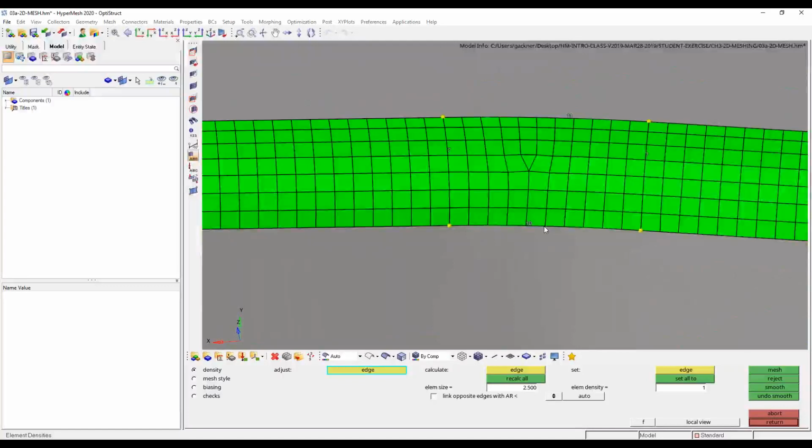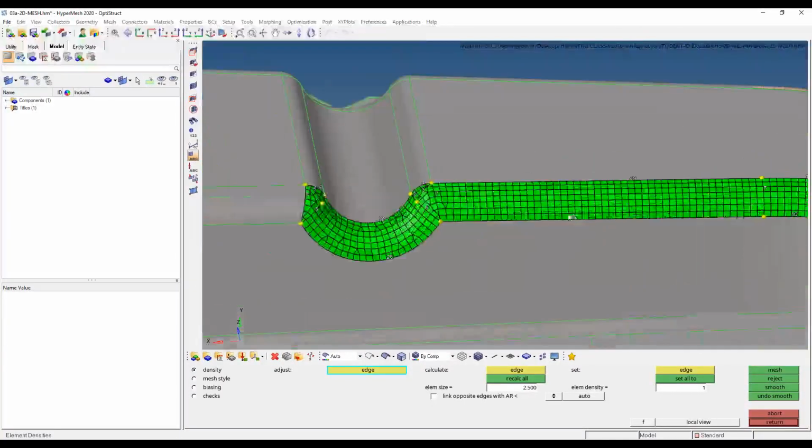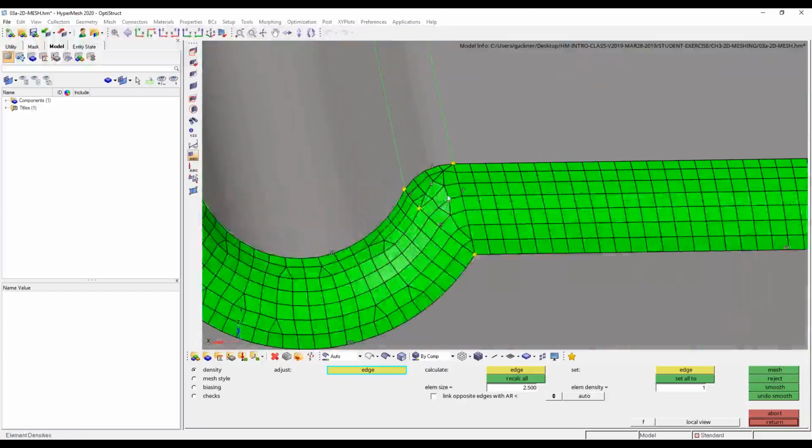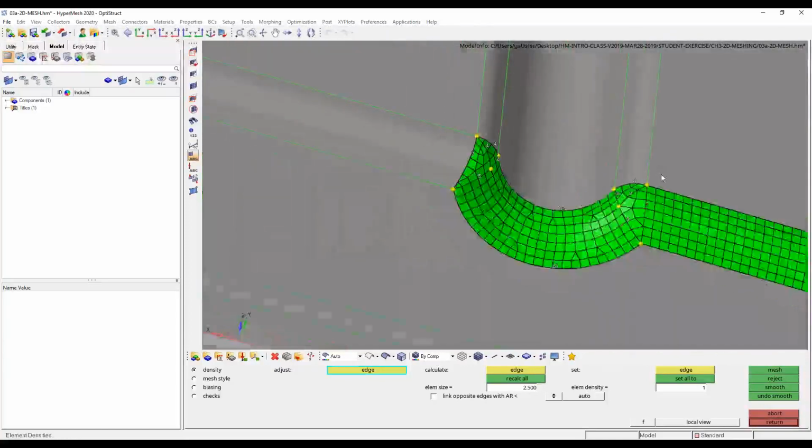Same thing over here. We have a fillet density that doesn't want to match up there. It's got 11 to 10. Now, given how many elements there are, I feel pretty good that I can bump that up to 11 or bump the other one down to 10 without drastically changing the element size, given that it's only going to change it by about 10% or so for that given region. So what's nice here is HyperMesh gives you some tools right away to just come in here and start tweaking with these elements while you're going through it.